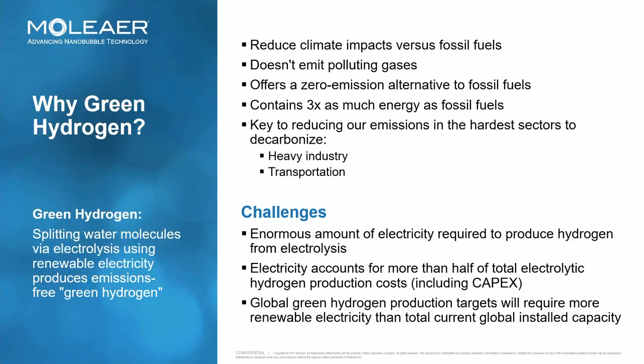We also are looking at hydrogen closely. About 2 years ago, we experimented with a very small electrolyzer. What would happen if you put these electrochemically active nanobubbles, in this case we actually used air, it didn't matter what gas we were using, into the electrolyte to see if it increases the charge density of the electrolyzer. And we saw some significant improvements depending on whether it was a PEM or an alkaline-based electrolyzer.